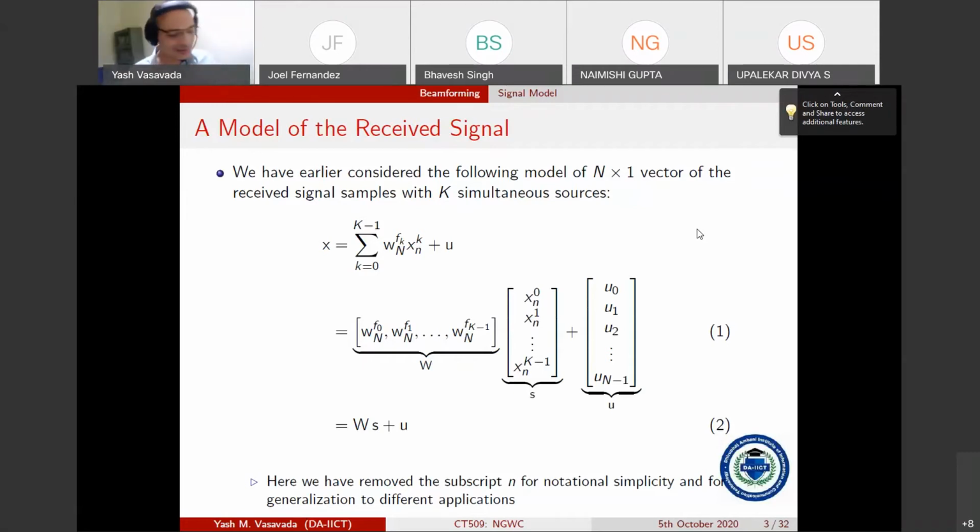But yeah, so the answer is 1 over square root of 2, 1 over square root of 2, because the second symbol of 8 PSK is 45 degrees from the x-axis. So its constellation point is 1 over square root of 2, 1 over square root of 2.